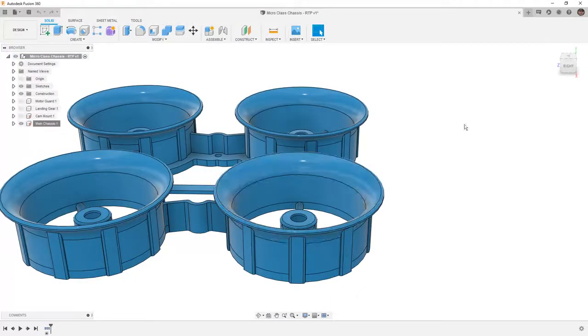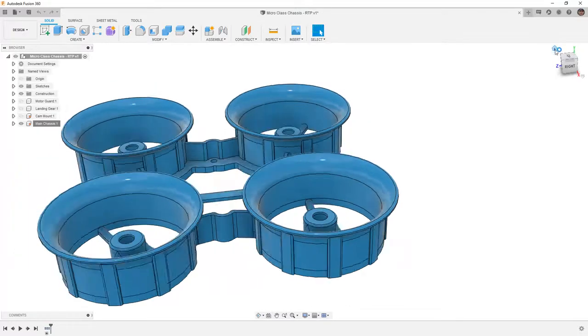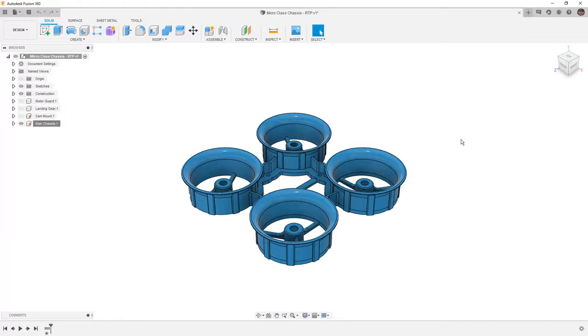It's a good idea for you to play around with this and bring these STL files into your print utility and get a good idea as to what these resolutions mean for your final prints. Anytime somebody is using a design tool like Fusion 360 for the first time and sending these files out to a 3D printer, I like to suggest that they make a sample file.